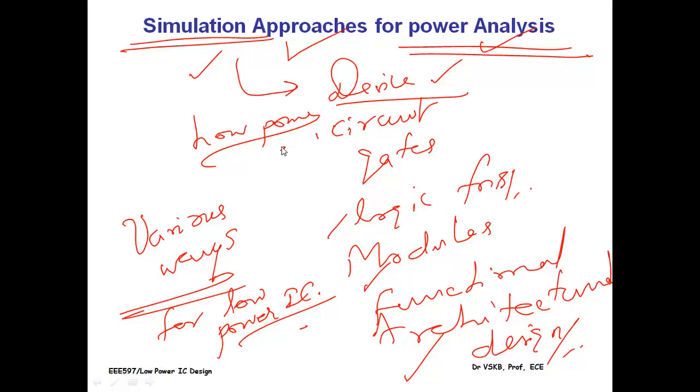And through these simulation based approaches, I go for making use of the EDA tools you had been using. For example, the Cadence tool what you are using, and the Xilinx tool what you have, Altera, all these, they have modeled the circuits inside, and the use of such idea is enabling us to go for analyzing the power what we have out of the circuit while operating under such conditions, under maybe even the temperature parameter, or the worst case best case models.